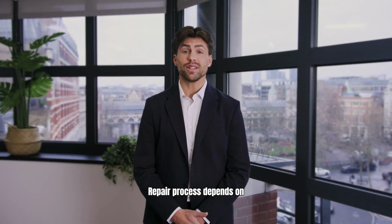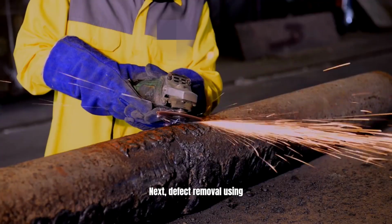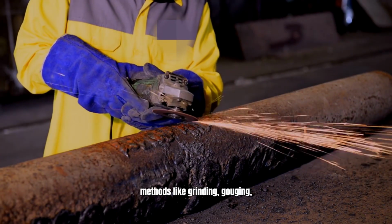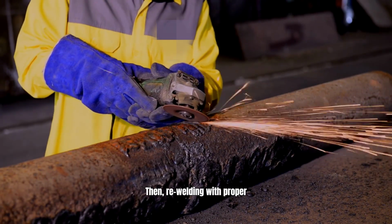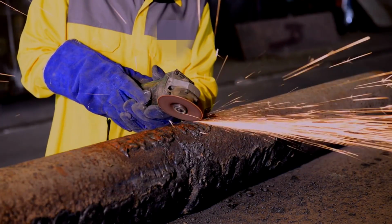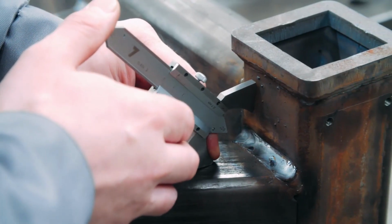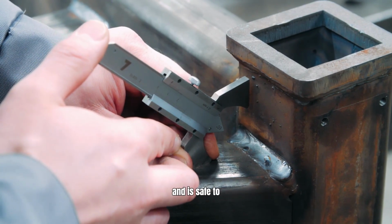Repair process depends on defect type. First, confirmation. Verify the defect by NDT. Next, defect removal using methods like grinding, gouging, or chipping. Then, rewelding with proper WPS, controlled heat, and correct filler material. Finally, reinspection. Repeat testing until the weld passes, meets standards, and is safe to use.